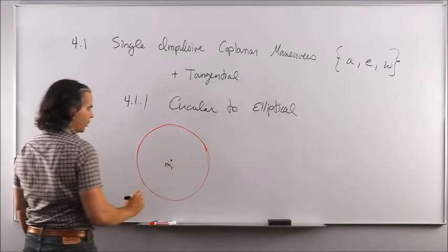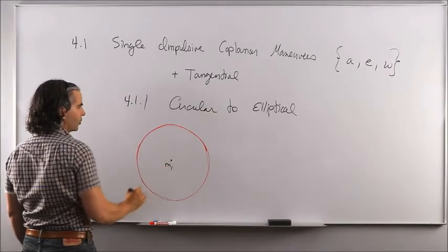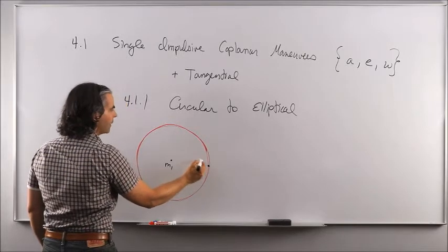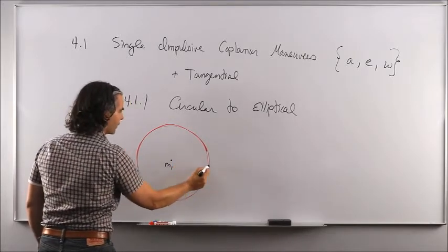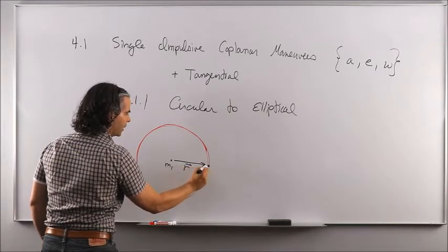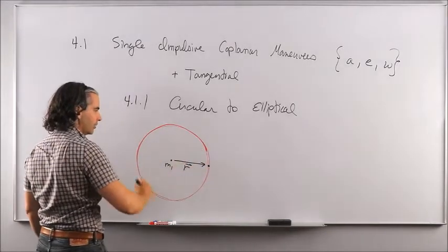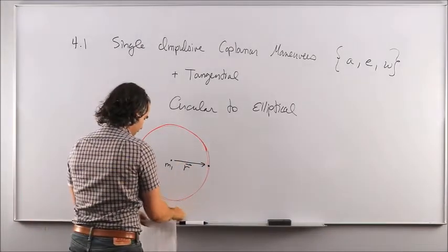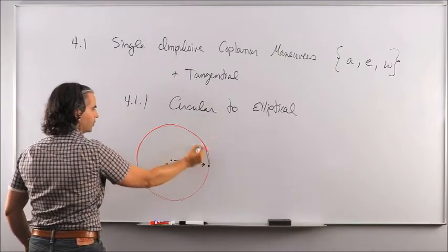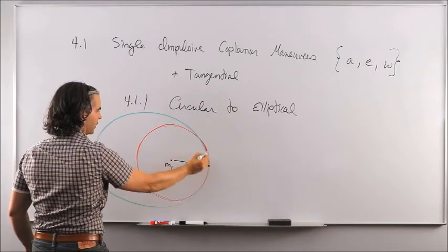Well, all you have to do, because the radius is constant at any point along this orbit, is to thrust at any point. I'm going to pick this one here. Apply a delta V maneuver such that this point now becomes the intersection of the initial and the final orbit, and kick us into an elliptical orbit, which would look like this. Okay?